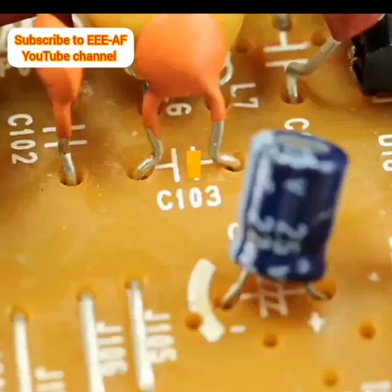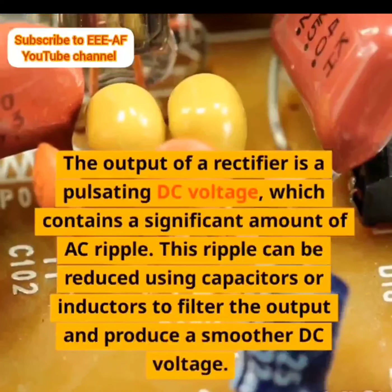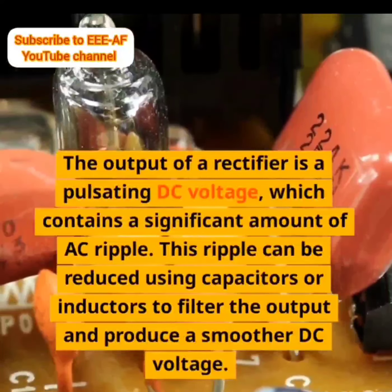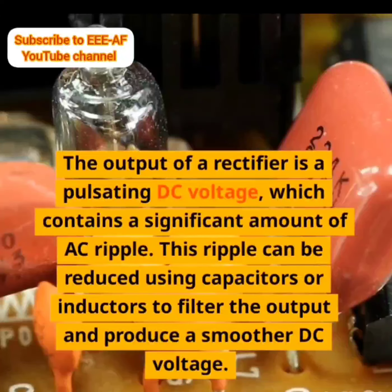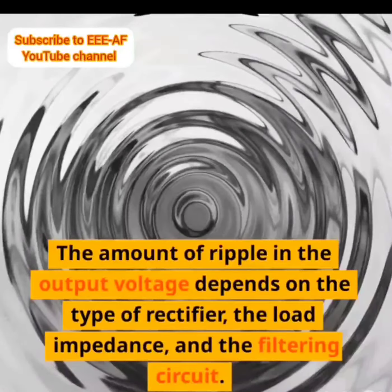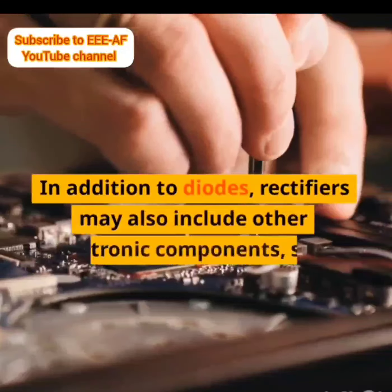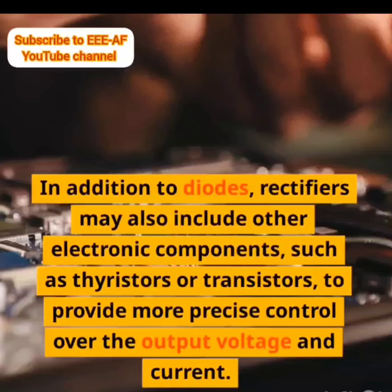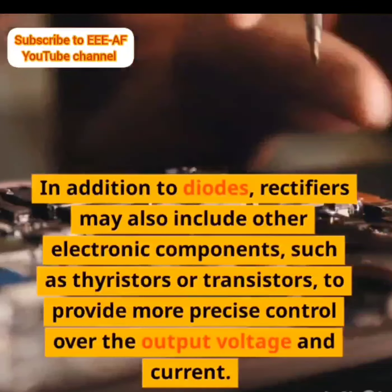The output of a rectifier is a pulsating DC voltage, which contains a significant amount of AC ripple. This ripple can be reduced using capacitors or inductors to filter the output and produce a smoother DC voltage. The amount of ripple in the output voltage depends on the type of rectifier, the load impedance, and the filtering circuit. In addition to diodes, rectifiers may also include other electronic components, such as thyristors or transistors, to provide more precise control over the output voltage and current.